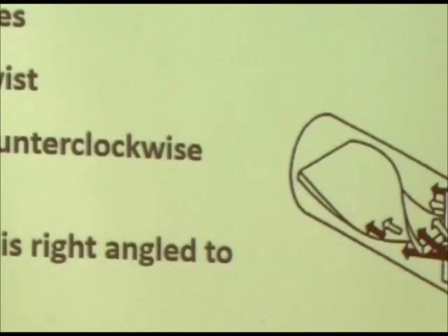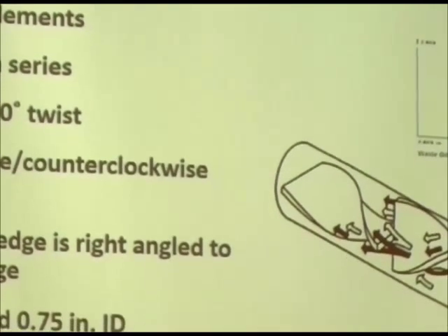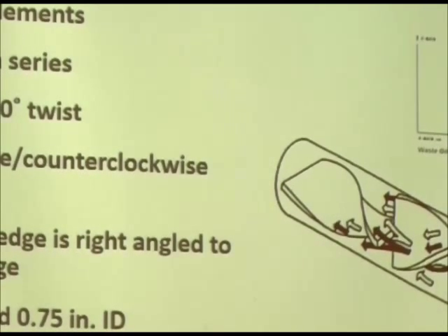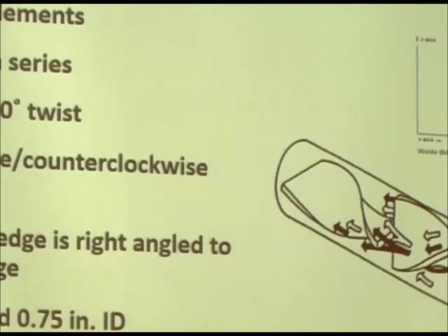We use a 42-inch static mixer altogether. It says 36 inches on there. The 36 inches was for one section, and there was a second section, a 6-inch section located inside the main reaction chamber. And they were both 0.75 inches in diameter. That is an inner diameter.